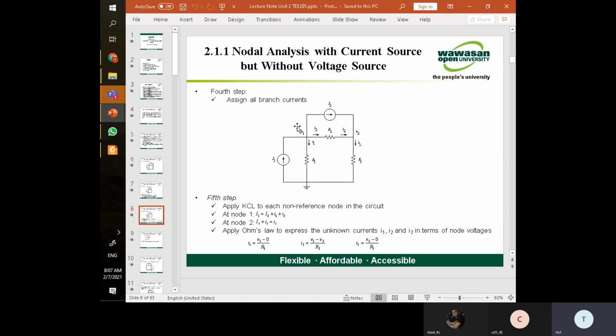So tutorial 2, the first part here, is about the nodal analysis. We base on the node here, for example V1, and then we start working out some of the currents using the KCL. Because the KCL is focused on the node, we're starting from here.